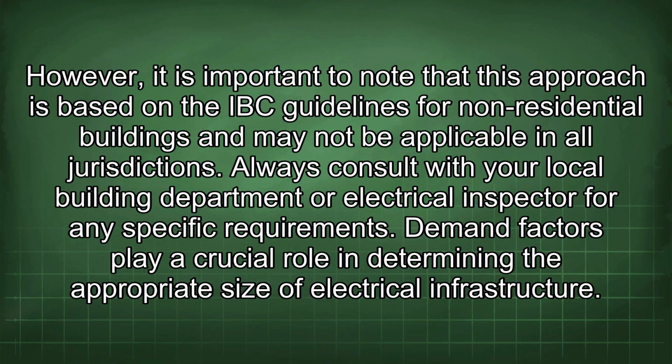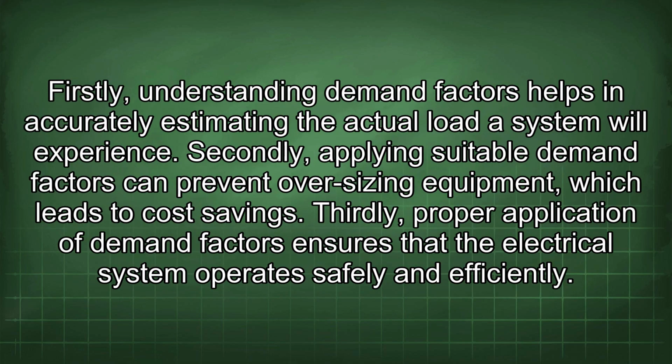Demand factors play a crucial role in determining the appropriate size of electrical infrastructure. Firstly, understanding demand factors helps in accurately estimating the actual load a system will experience. Secondly, applying suitable demand factors can prevent oversizing equipment, which leads to cost savings. Thirdly, proper application of demand factors ensures that the electrical system operates safely and efficiently.